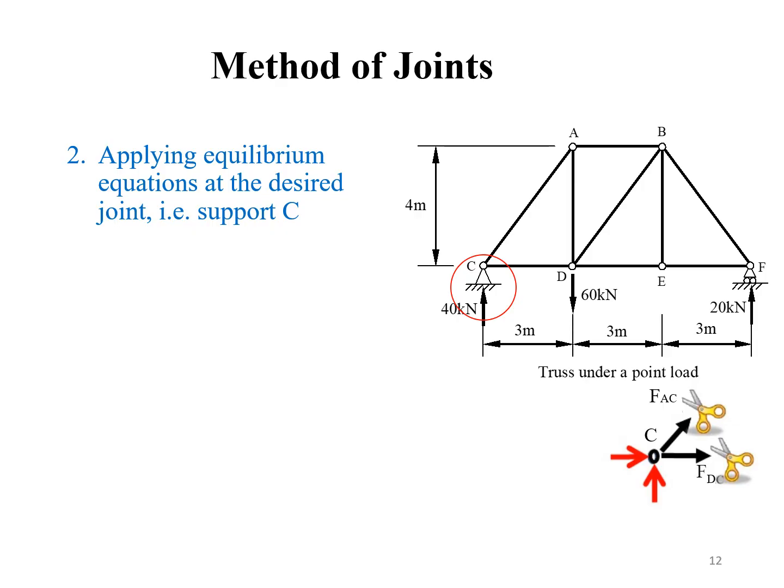Now let's determine the forces acting on each joint. Please see the figure. Since we don't know yet which members are in tension and which are in compression, it's easiest to just assume that all of the members are in tension, and so we will draw internal forces as pointing away from each joint. If we end up with negative values for these forces, it just means that we guessed wrong, and the member is actually in compression. Now we can work through each of the joints, starting with joint C.